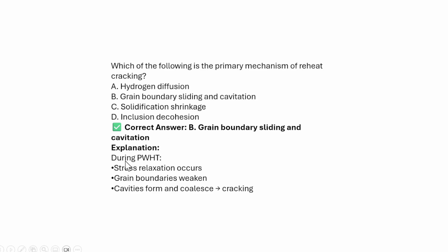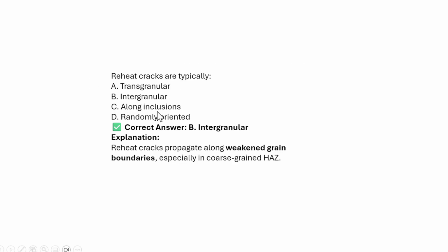So during the post-weld treatment, stress relaxation occurs, the grain boundary weakens, cavities form, and it will result in crack formation. Okay. Next,